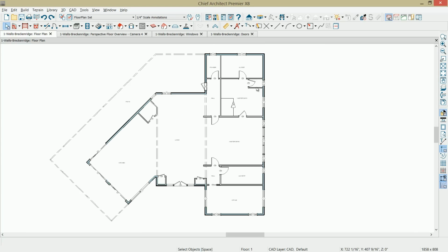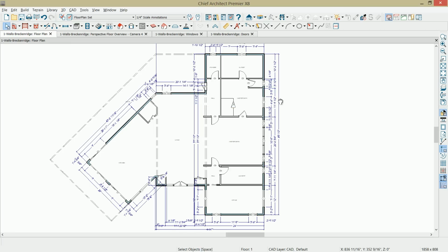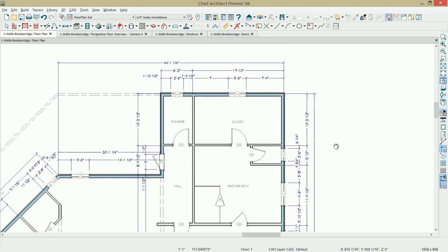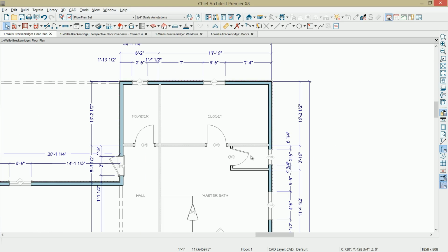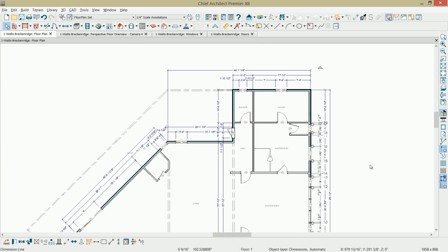Now the last step in the process of creating the floor plan for floor 1 here is to update your automatic exterior dimensions. Click on that, turn the layer back on, and a lot of times you'll need to zoom in here and maybe clean up the dimensions. Depending on what that is, you'll notice that maybe my openings here didn't go all the way to the end of the wall like I wanted it. So you can just simply click on the dimension. You always find an extra diamond that you can come in, pull that over, and likewise you can also pull those diamonds off.